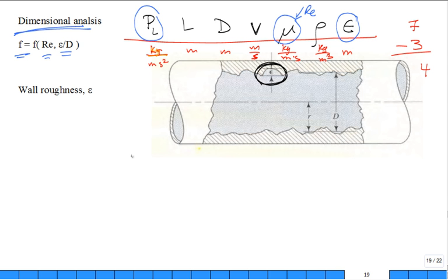If you say that you have the pressure loss and it's a kilogram per meter second squared, I want to get rid of kilogram using rho. So let's put 1 over rho, kilogram per meter cubed. That work? All right. So we got rid of the kilograms.